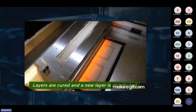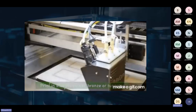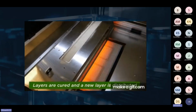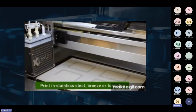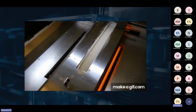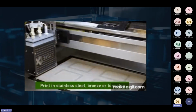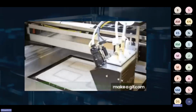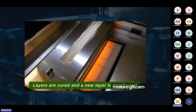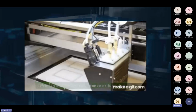After the powder is layered down, the equipment spreads the binder material in the desired shape on the first layer, and next, light is used to cure that binder material, and then another layer of powder is placed on that. This binder material acts as a binding agent and joins these two layers. This process repeats, and once all layers are done, the total product is post-processed and we get the final product.